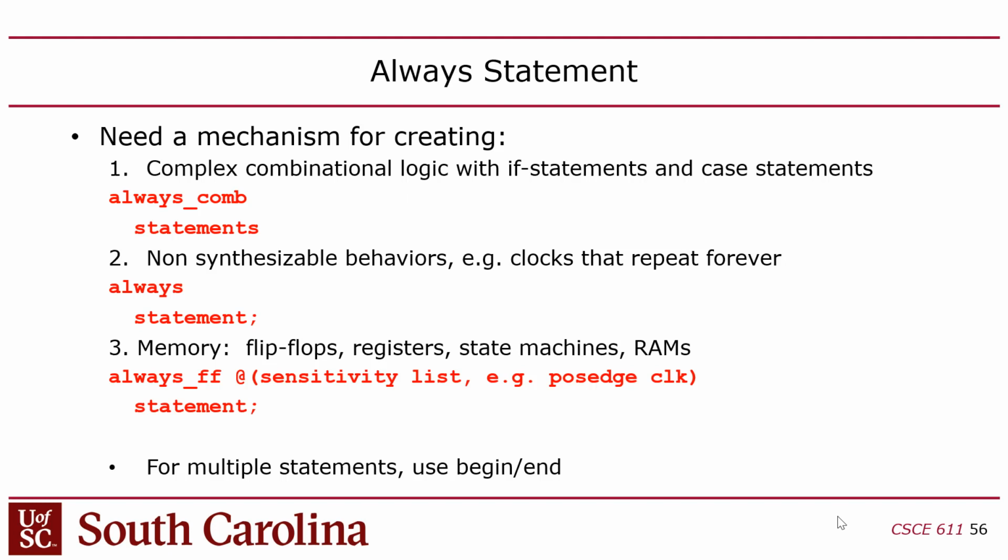So what does that mean? It means that F is something that's only being read when C or D are set to some value, right? Does that make sense? So if you're making combinational logic, you want to make sure that you always use always at star, or always underscore com if you want to use the newfangled SystemVerilog syntax. Always com is safer, because always com doesn't have a sensitivity list, so there's no way to make a latch that way by forgetting an input signal.